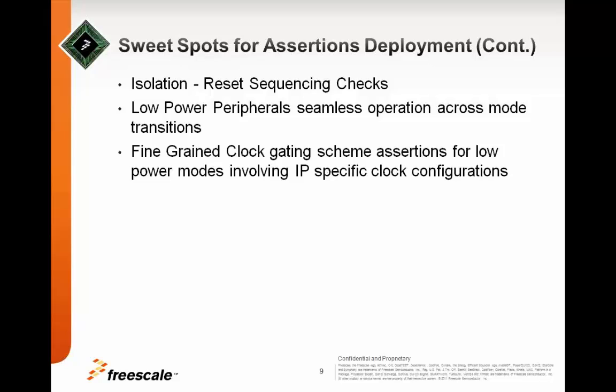We also have fine-grained clock gating scheme assertions for the low power modes, wherein within the low power mode we have another level of granularity wherein we can control, configure and gate the low power peripheral clocks by configuring the clock configuration registers. Again, we deployed the low power assertions here to check the fine-grained clock gating scheme for all the low power peripherals in the design.